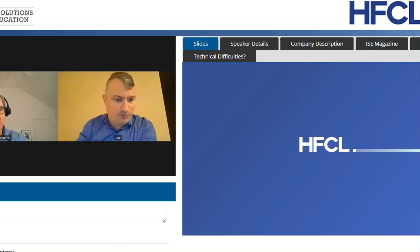That is the most common. I mean, the question is, how many poles do you have and how far are they apart? But if it's NESC heavy and you are more than about 50 and the poles are more than about 40 meters apart, you're kind of stuck with strand and lashing.